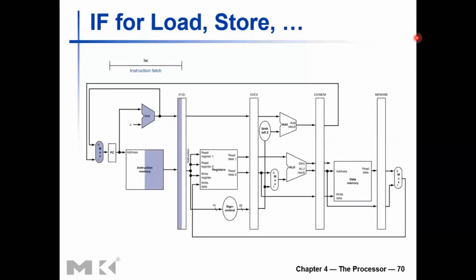So don't we have to store the control signals also, because they are also getting manipulated, right? Yes, but do we have any control signals generated for this instruction yet? We don't. Those signals are generated when the instruction moves into the next stage. But what you're asking is a very good question. After the next stage, you would have to be concerned about that as well. For now, in the instruction fetch stage, in this particular clock cycle, you don't have to worry about the control signals.